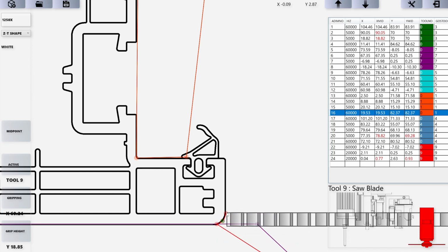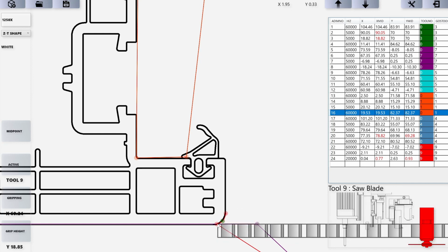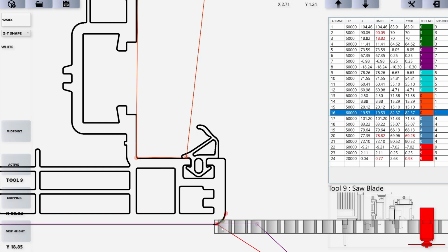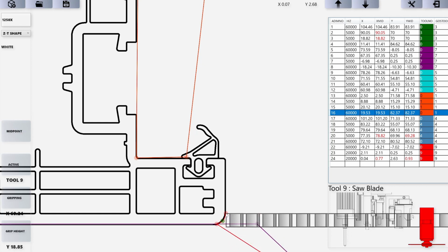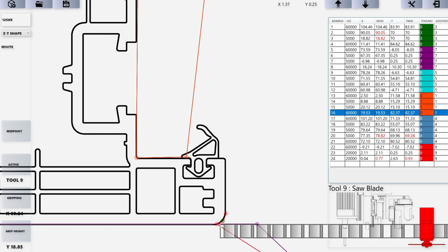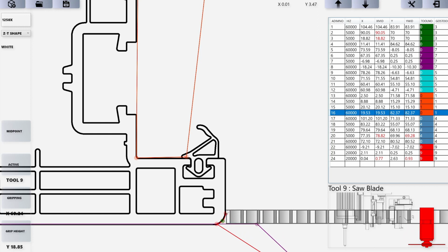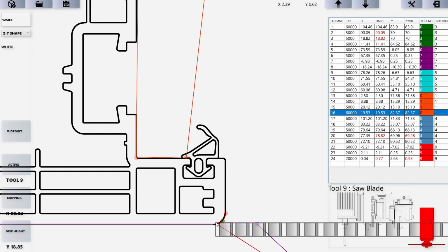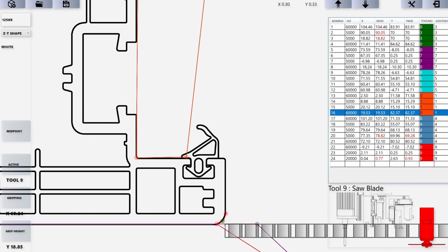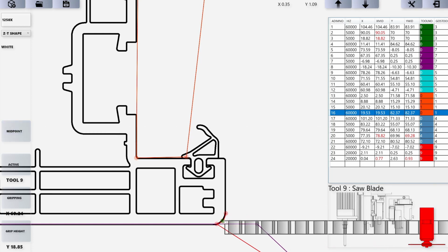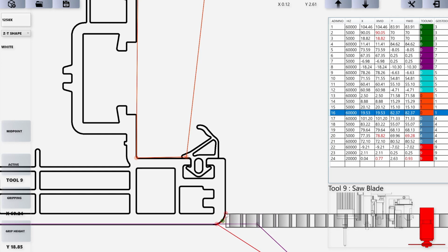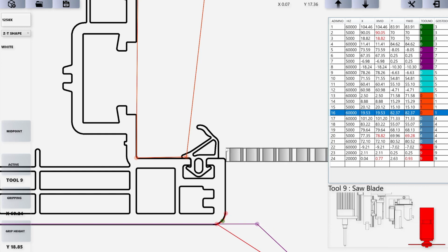After you make the third point, you make the first, click midpoint, make the middle point, and then you click on the final point. So with 3 points, you create an arc: the beginning, middle, and the end of the arc. So don't get confused here. When you make the first one and click middle point, it will ask you for 2 more points. So the first one will be the middle, and when you click again, it will be the final.